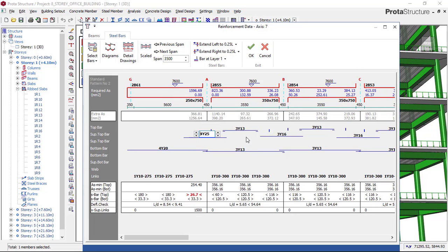You can see that right now. If at all this place was still failing, we would increase our beam to at least 850, and if it's still failing, 900. So right now we're going to change this place to 16 numbers; a 16 diameter of bar will be okay for this place. We'll change from 13 to 16, and make sure you're checking all these areas of bar if they are 175, which is okay.